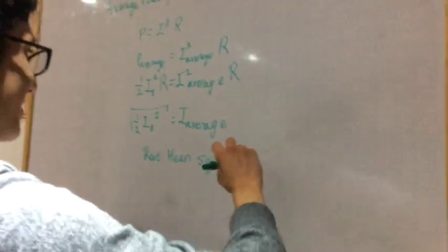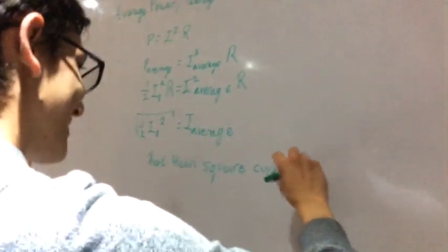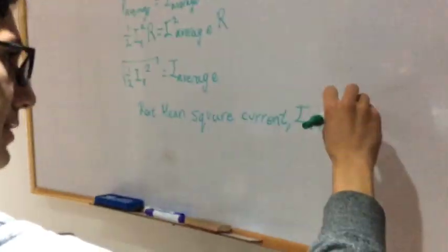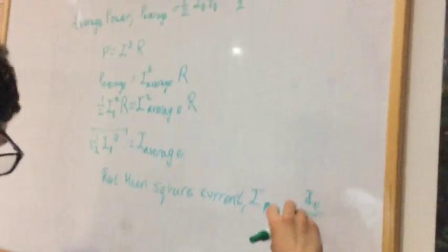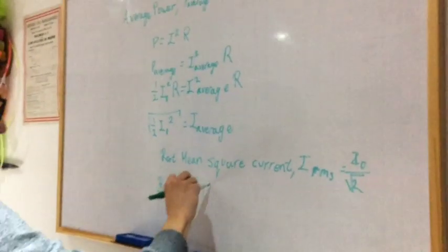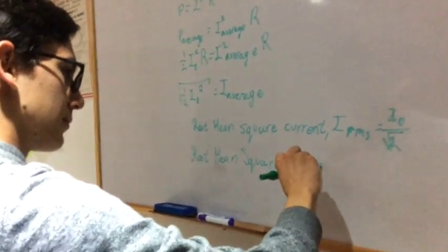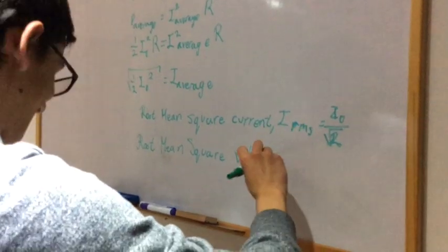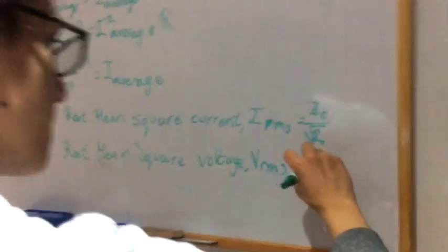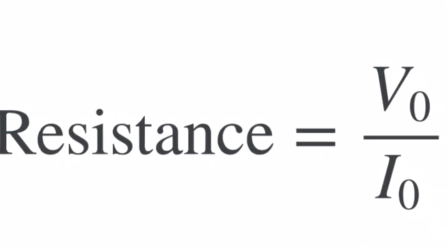Likewise, the resistance will be a ratio of the potential difference to current in both formulas, as shown in the relationship. Resistance is equal to peak voltage over peak current, which is equal to root mean squared voltage over root mean squared current. After all of this, we get the term root mean squared. This way we say that the root mean squared of an alternating current, or EMF, is the value of direct current, or EMF, that will supply the same power in a given resistor.